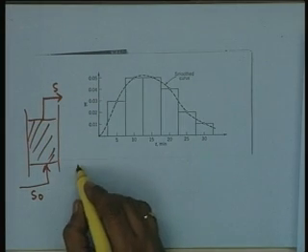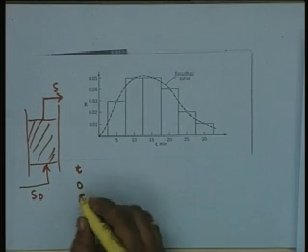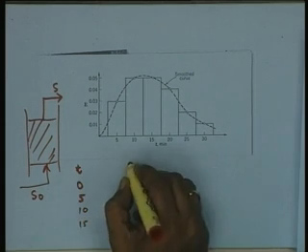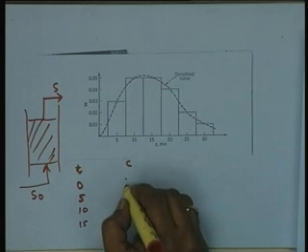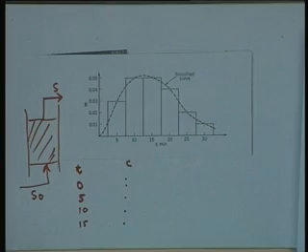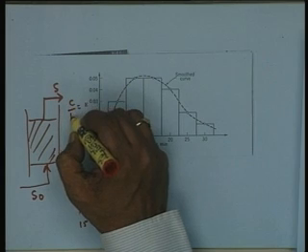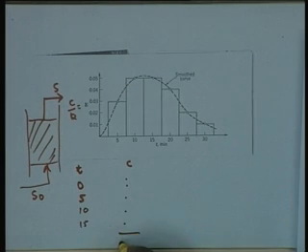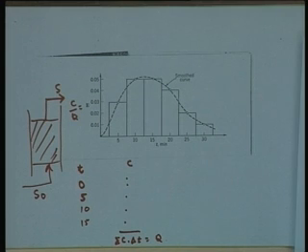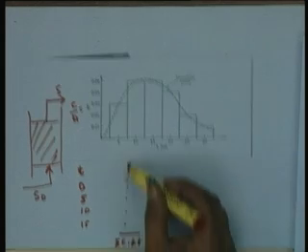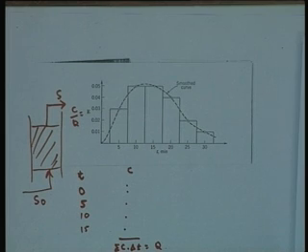Now, at time t equal to 0, 5, at equidistant times, you determine the concentration of the tracer, whatever values come at equidistant times, and they are plotted again in terms of C upon Q. That means you consider the sigma C delta t as equal to Q. Essentially, here is also a check: this sigma C delta t of all the data must be equal to the actual quantity of tracer which has been put in.